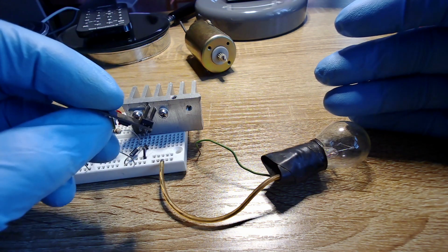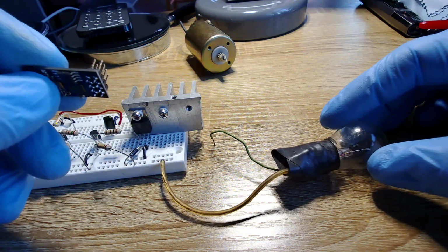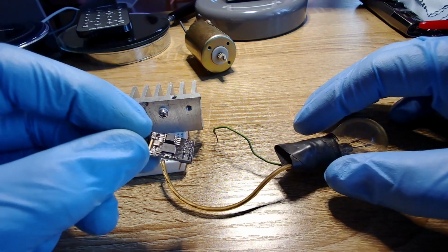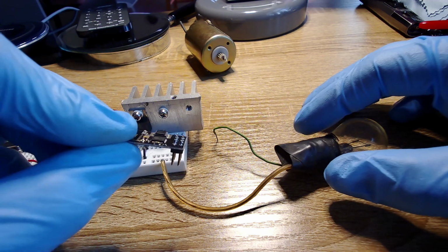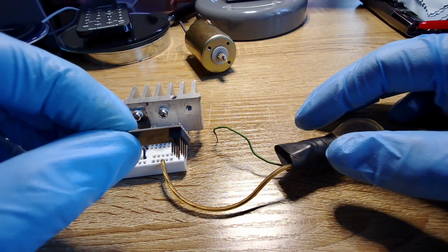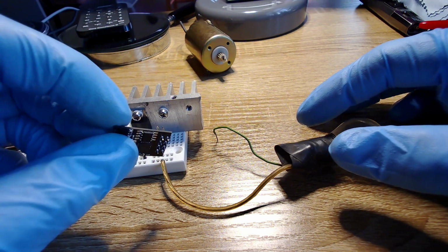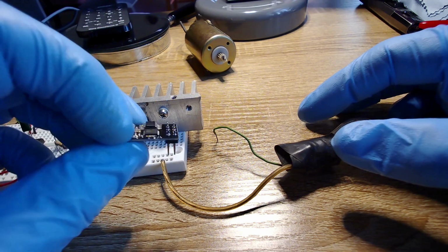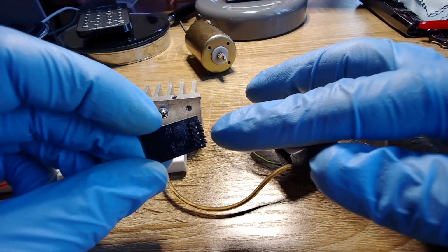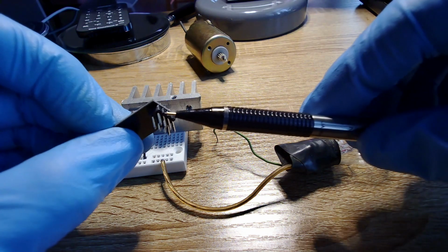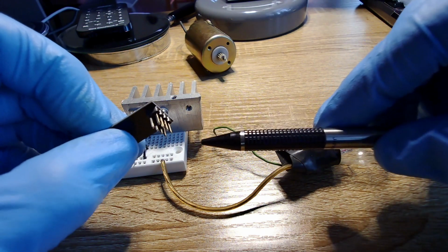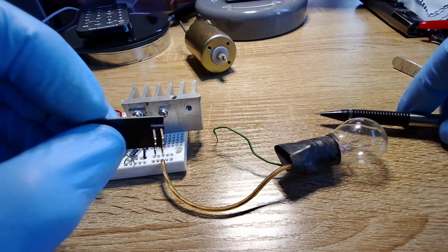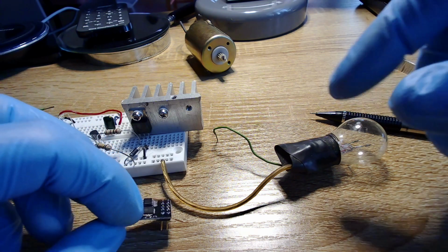This thing is nowhere near going to be anywhere near 13 volts. It can't hold 13 volts up there to run anything. And look at this thing. This has no capacity for current or power. This thing's going to get fried if you try to move anything through this. So all this thing can really do is say, yes, I want it on, or I want it off, and tell us somehow. It'll tell us on one of these pins by giving us a 3.3 or a 5 versus 0 volts, right? 0 or 1. In digital, we all know that, 0 or 5 volts, or in this case, 3.3.